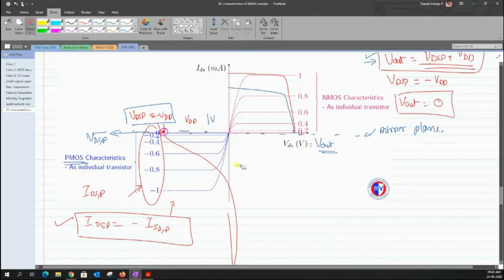Maybe I can work it out with respect to the NMOS. I discussed the same thing, because the graph of my PMOS is inverted, it becomes hard for us to really visualize that. So let us assume that I have this kind of curve. We know that the value of VGS that I have is more positive, but still it doesn't conduct any current. In this case, you could see that there is some amount of current flowing through the device, and the corresponding value of VDS is defined by this particular x-axis. If I choose this as my current, the corresponding VDS value is defined something like this.